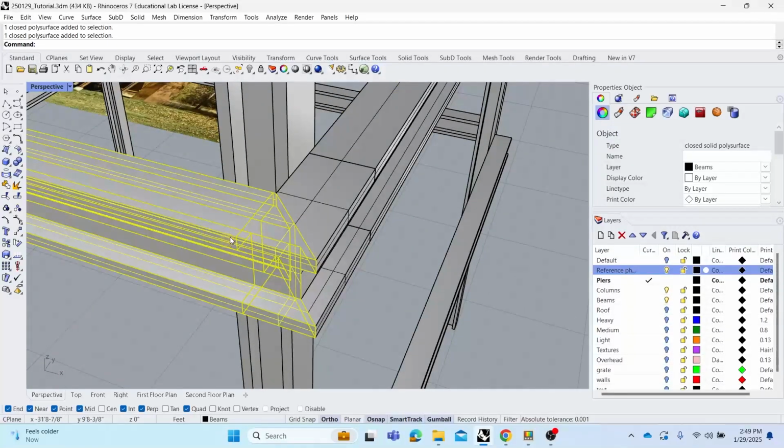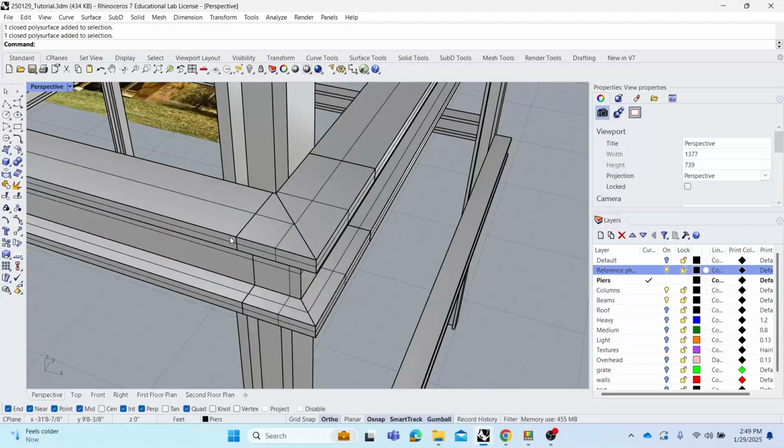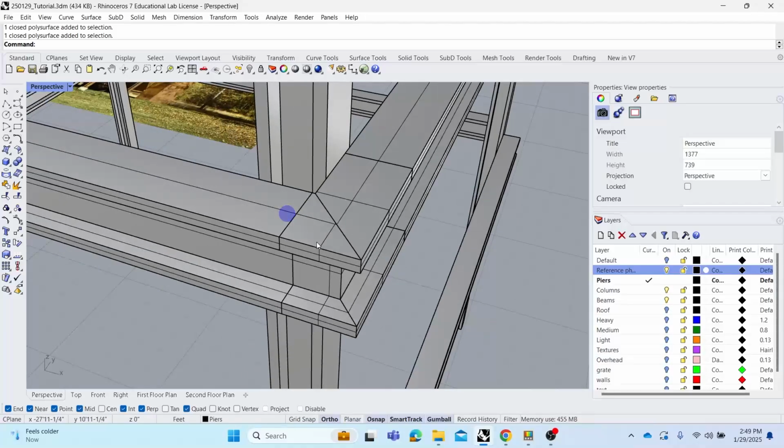One graphical thing, maybe frustrating to everyone, I know it is for me, is seeing these display lines that intersect the nice clean shapes. It's just due to the fact that when you Boolean union things together or extrude surfaces from an existing surface, it reads it as a new instance or a new part that has been added to the original.